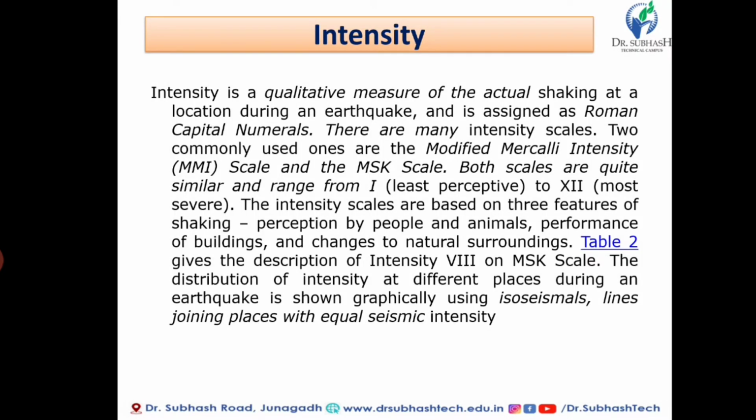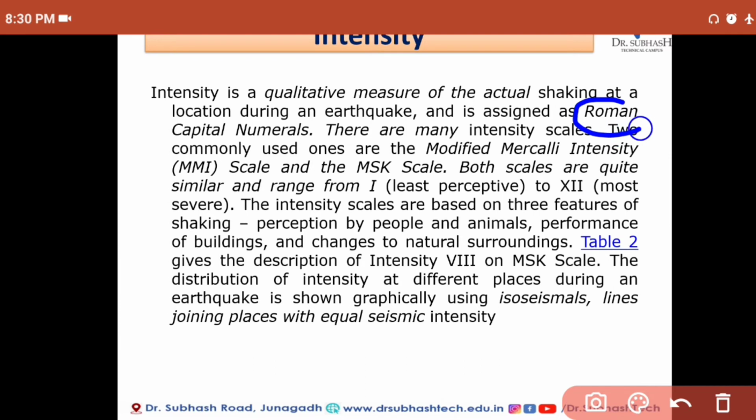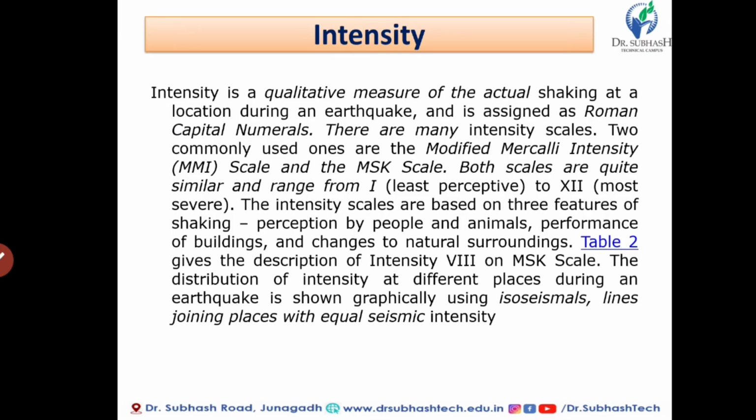So now intensity. After the explanation of magnitude, you can visualize one scale about magnitude: what the energy release should be for an M6.6. Now what is intensity? This is the second approach to measuring the earthquake, and it is a qualitative measure of the actual shaking at a location during an earthquake and is assigned a Roman capital number. Here I highlight that it is assigned a Roman capital number.